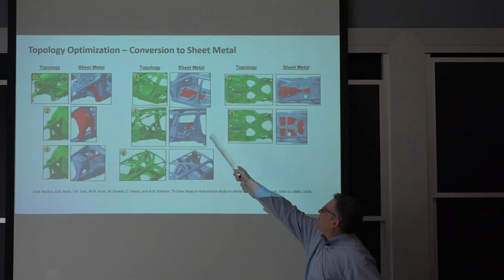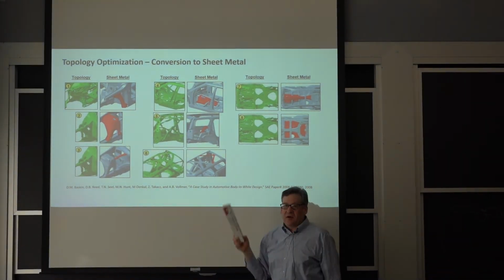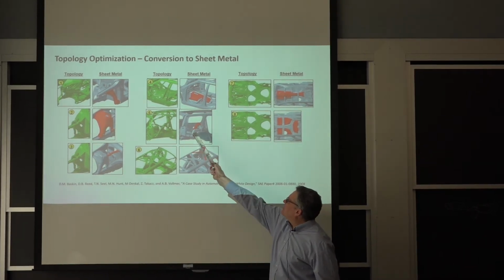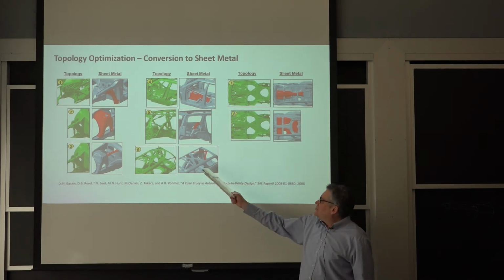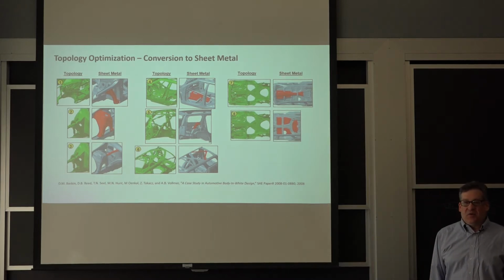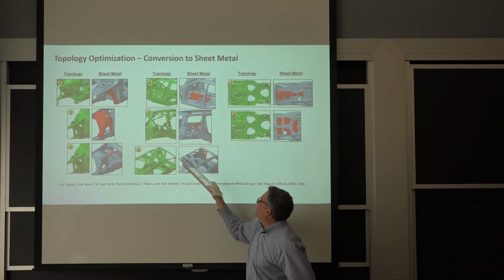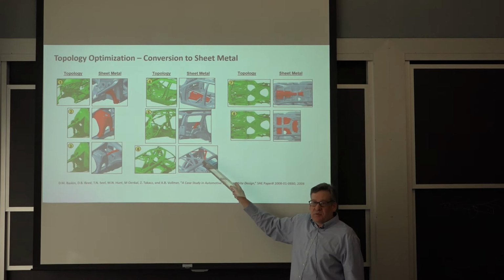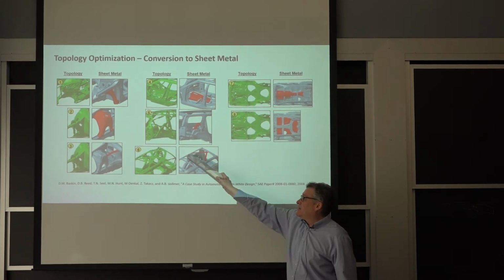So the side of the tunnel, we saw these spider web structures. We tried to duplicate that with these ribs. This load path that goes from the rear shock tower to the C-pillar, something we added. In the roof structure, you end up seeing a lot of K's and X structures. Okay, so this is, for example, this K structure right here. Here's an example of a K structure. We added that, and it's enormously effective at increasing the torsional stiffness of the body structure when you can put something like that in there.